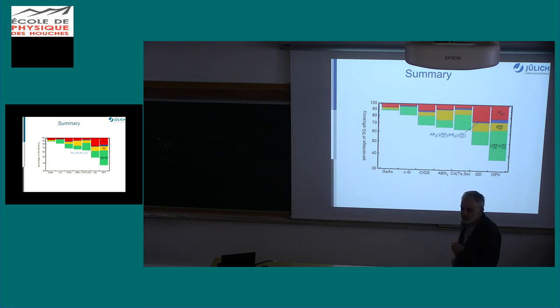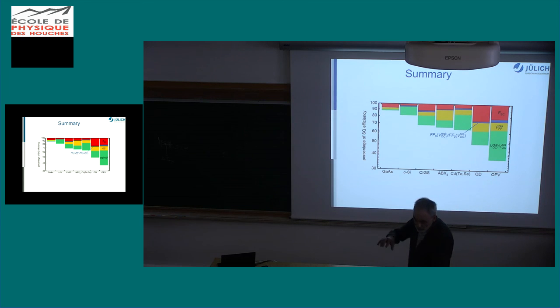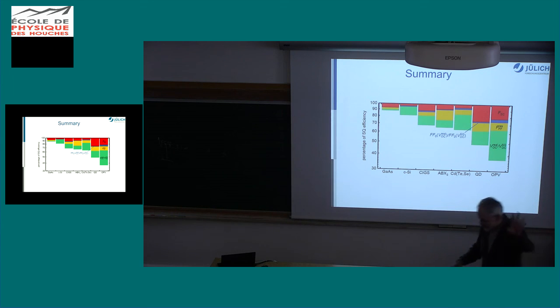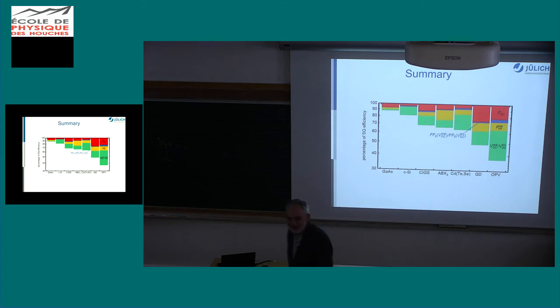The tricky thing comes with the J naught, the loss, because if you add this multiple carrier generation, that's another gain path. By the principle of detailed balance, if you have a gain, you also have a loss. So you have to include the inverse of that very process in your calculation. That gets tricky on the J naught, but I'm sure Jean-François will give you the proper equation on Friday.